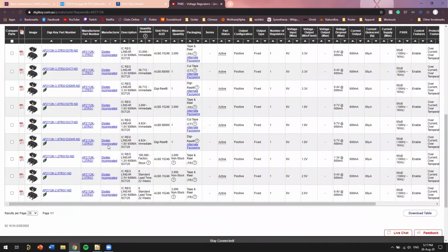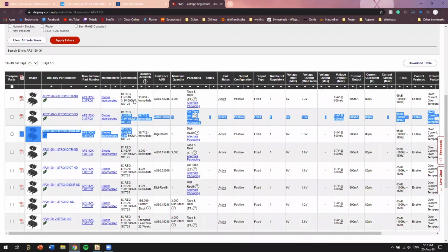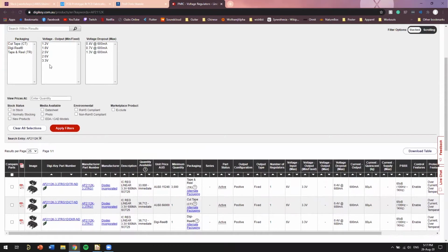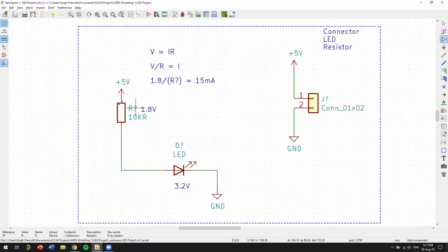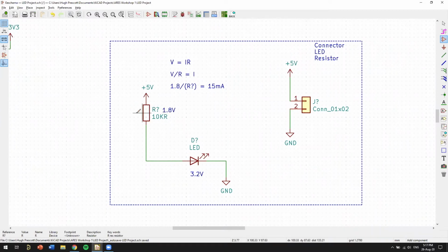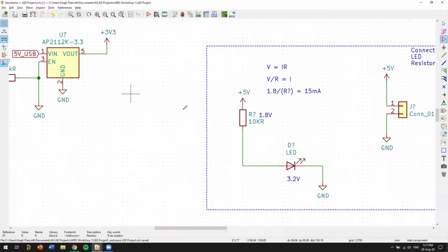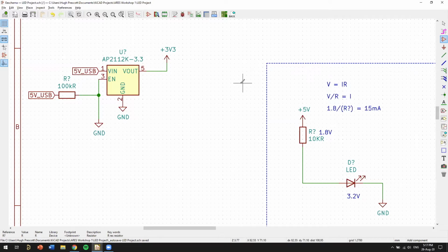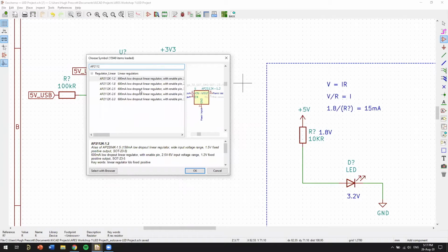And the differences here, this one here is a 2.6 volt regulator, 2.5, 1.2, 1.8, 1.8, 3 volt. So we want a 3.3 volt regulator. Actually, sorry, I'll talk about this later. But the point is, for these passive components, you can just put down a very standard schematic symbol, and you can swap out to different part numbers. But for complicated parts, you can't do that. And all of these exist within KiCad's library, which is, I guess, the main point of this.